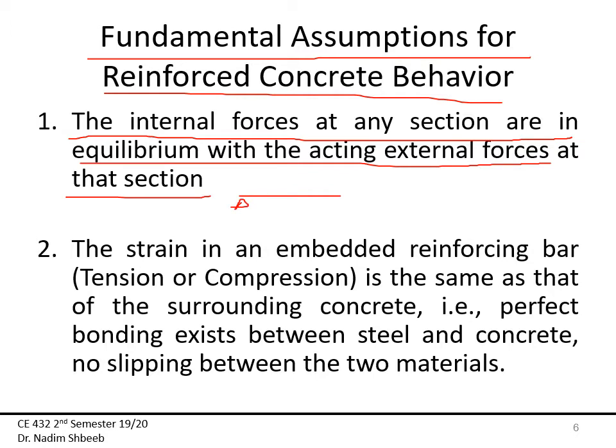Meaning, let's say I have a beam like that and I have a distributed load W, then the applied load would give me a moment of WL squared over 8, the maximum moment, at this section here. We know from strength of materials that my stress is equal to M times c over I. So that internal stress that is generated is from that moment, which is equal to WL squared over 8. And I'm going to show you in a couple of slides how we're going to calculate this internal moment, but it must be equal to the applied moment. So it's just pretty much static equilibrium.